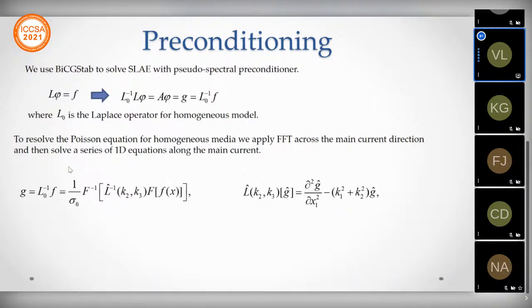And the standard approach to precondition the Poisson equation is to use multigrid. But the problem in our simulation is the complexity of the domain geometry. Using multigrid, coarsening the mesh would cause the model on the coarser mesh to have a completely different topology.